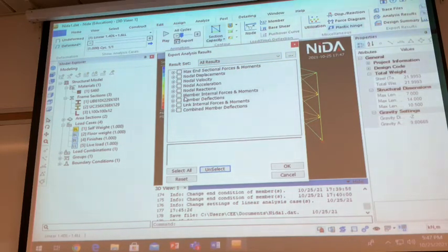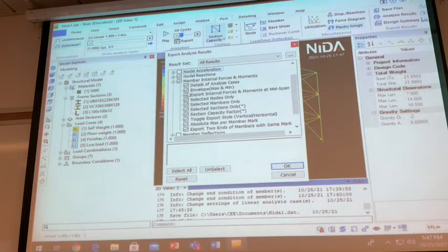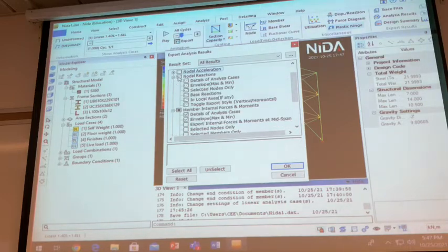This page is what you want to output, what you want to read. So probably I like local displacement. I want to check the serviceability. If this is the serviceability state, then you need to check this one. Check reaction, check envelope. Or perhaps I don't need to check all. I need to check the envelope and the maximum length. Or for the reaction, I check.